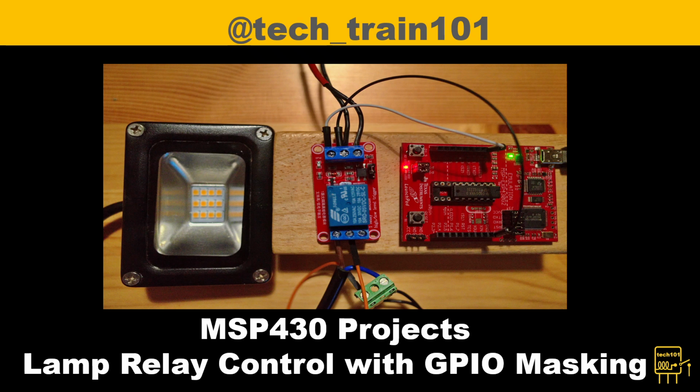I am going to present a MSP430 Launchpad based 10 watts lamp control microcontroller project using a commercial relay. We shall be focusing on GPIO manipulation and how C language bitwise operations can be used to effectively isolate the required GPIO by masking technique.